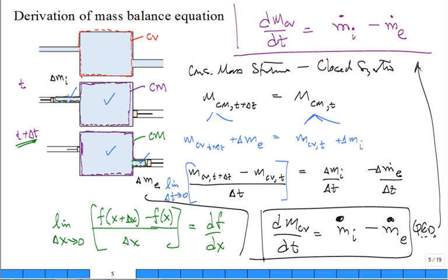That may leave you a little cold, right? But now we need to do the same thing for energy. The same thing for energy, because we can write an energy balance equation for a fixed amount of mass for a closed system, and we need it for an open system. And in that process, we're going to come up with H. Oh, that's why we need enthalpy, that new property, that very useful property, which is U plus PV. The internal energy plus the flow work term. Ready to do it?